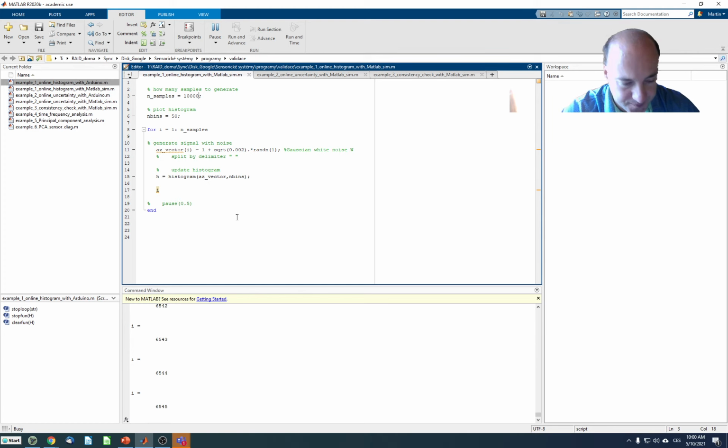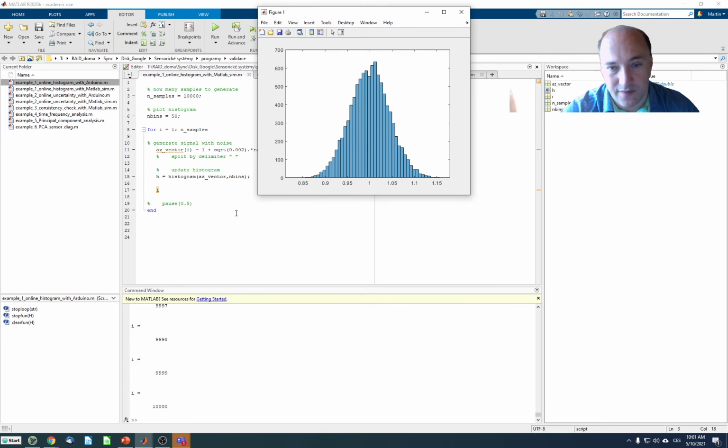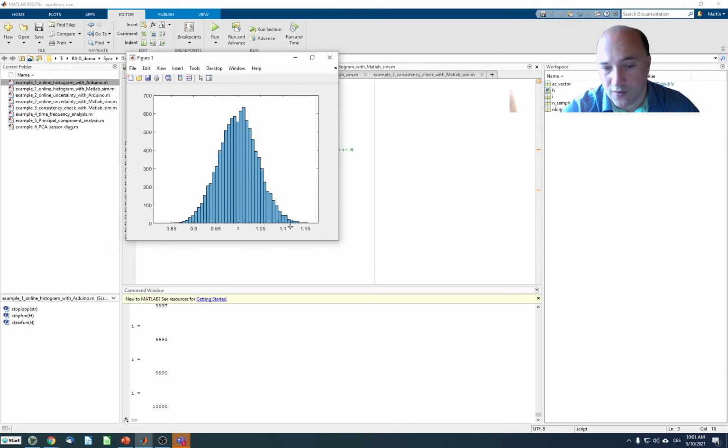And this problem might not be only a problem with the sensor. It might be completely unrelated. So for example, you may have a problem with interference that is coming from some motor, and at times when the motor is running, you may have this interference which will add noise to your measurements. This can happen typically in sensors that produce small electrical signals, such as thermocouples, for example, or strain gauges, because here we're talking about voltages somewhere in the order of microvolts.